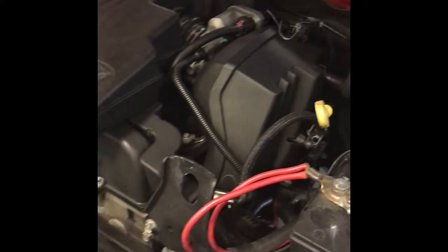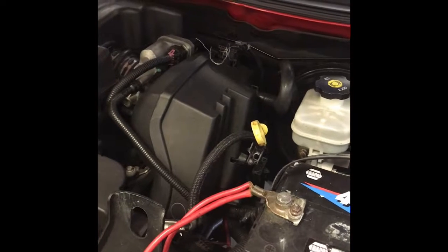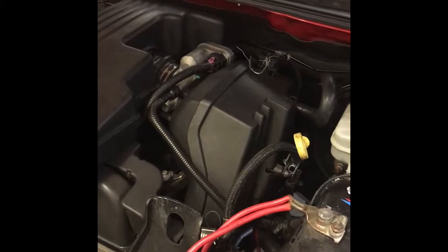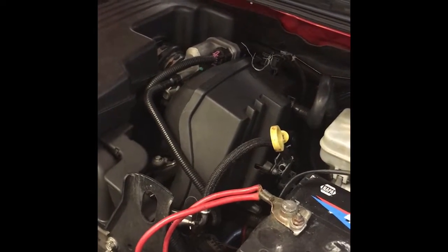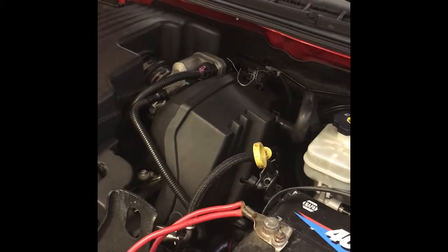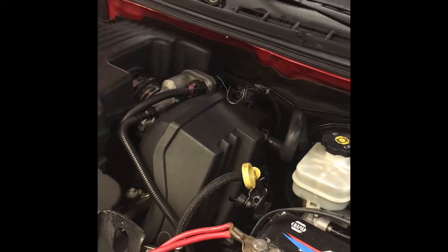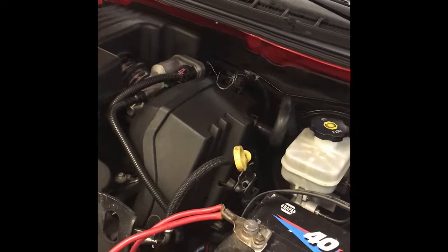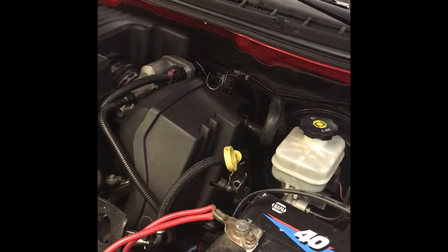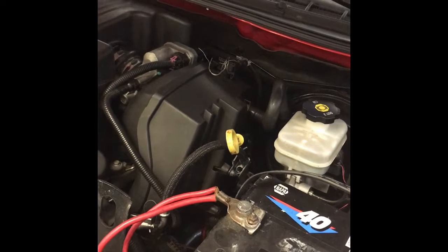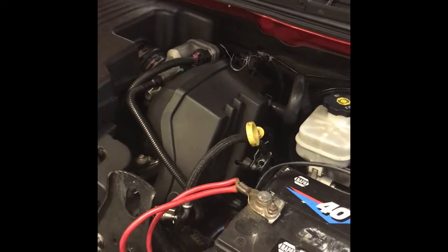It's important to maintain your vehicle by performing regular maintenance, to include your fluid changes such as your oil, your brake fluid, your power steering fluid, and such things. The transmission would also need to be serviced as per the service manual. You want to make sure you also check your wheels and tires on a regular basis, have them serviced, balanced, and rotated when necessary. Your cabin filters need to be checked. Power steering needs to be flushed, and you need to check the belts to see if they need to be replaced. Like I said, you need to maintain your vehicle in correct working order by conducting all the recommended services.